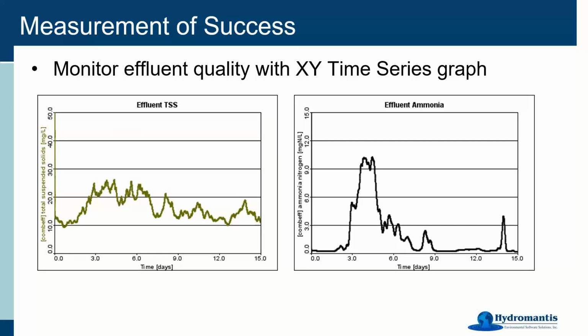Okay, so that's the first two steps. The third step was a way to monitor the things that you want to pay attention to, the information you're getting out of the model that will help you decide whether what you're doing could be better. You're going to monitor your effluent quality, obviously. You're going to want to plot things like the concentrations in the effluent over time. So for the base case demonstration that we're going to be doing here today, this is what the effluent quality